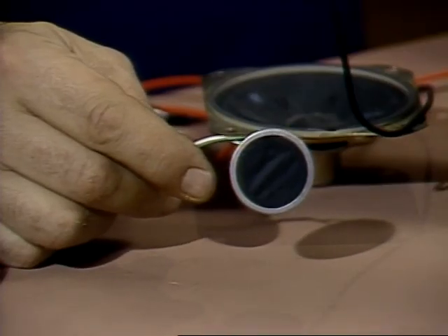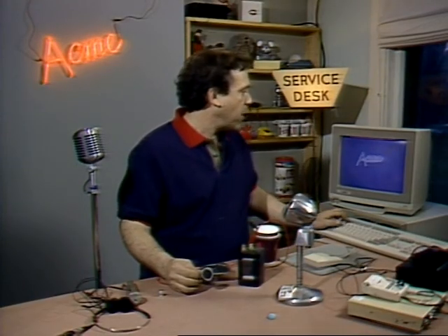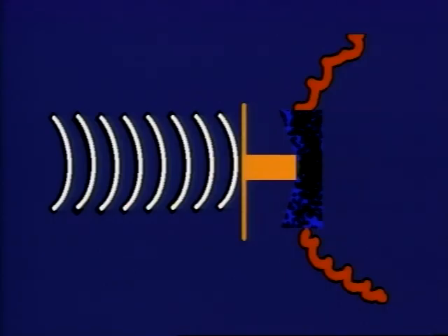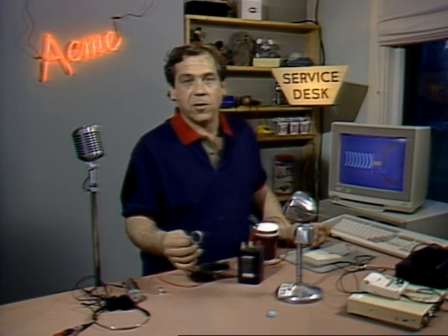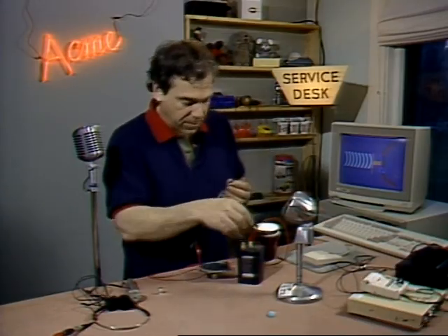This is Tom Edison's carbon microphone. It launched the telephone system and modern broadcasting. Inside is a bundle of loose carbon grains. A diaphragm like your eardrum is connected to the carbon grains so that it compresses and decompresses the grains according to the sound waves falling on it. The amount of electrical current that the grains will pass is proportional to the amount that they're squeezed. The wiggling electric currents that this produces are an analog of the sound pressure wiggles that hit the diaphragm.